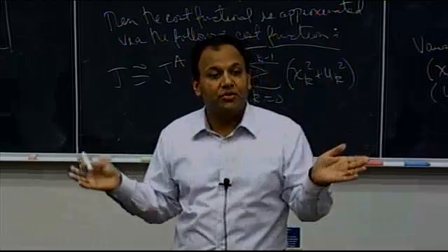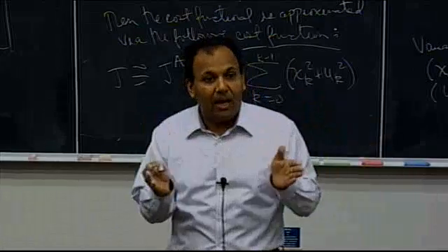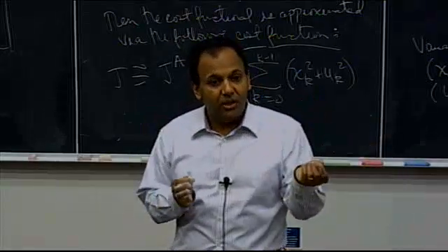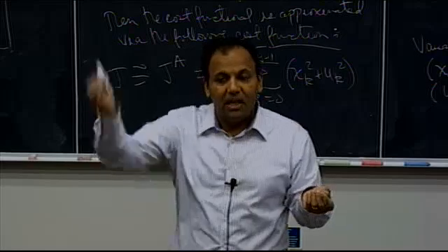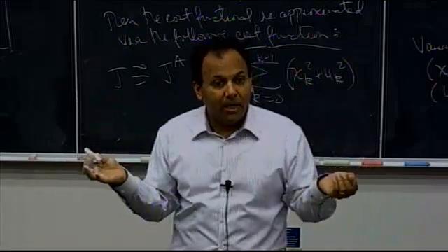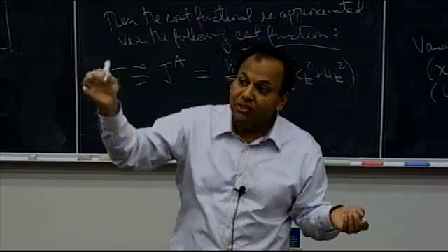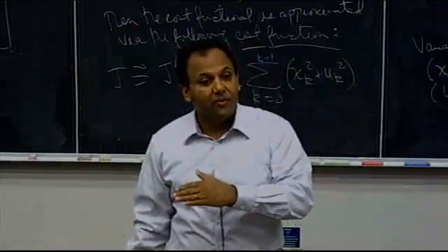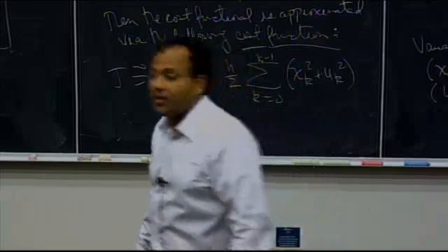How many values of the control do I have in this problem? I have k, right? The initial condition, and then I've got the final condition, right? So if I didn't have the final condition, I would have k degrees of freedom, right? But I've specified the final condition too. So I've removed another degree of freedom. So I have k minus 1 degrees of freedom. So I've got more variables than constraints, and I've got degrees of freedom.